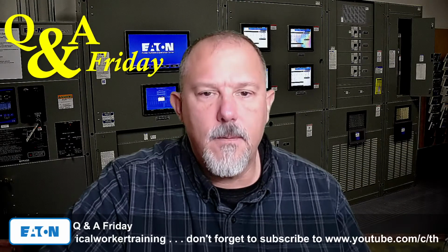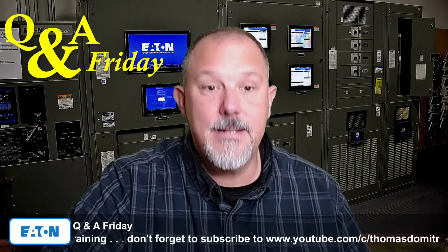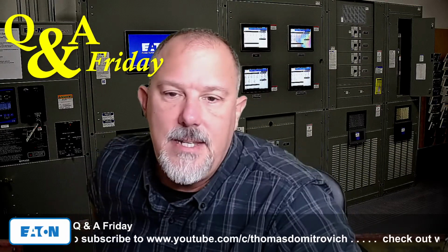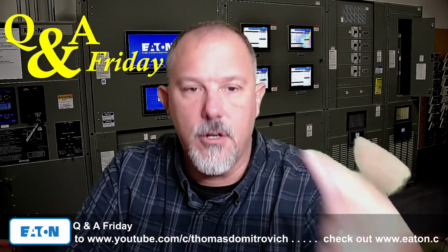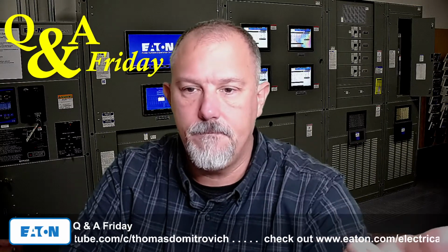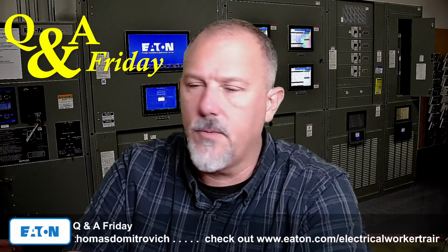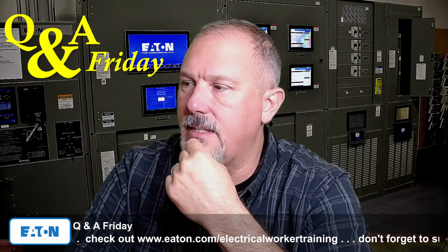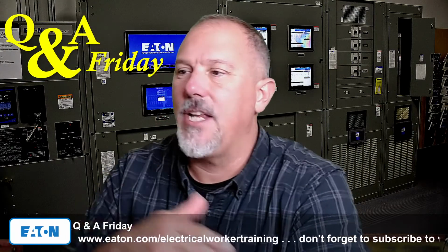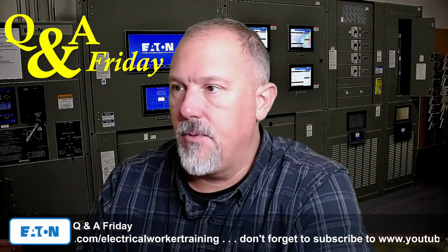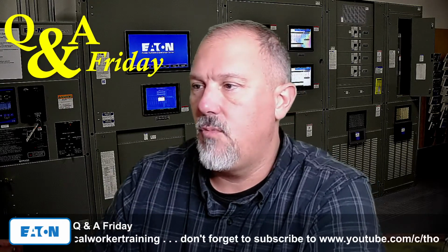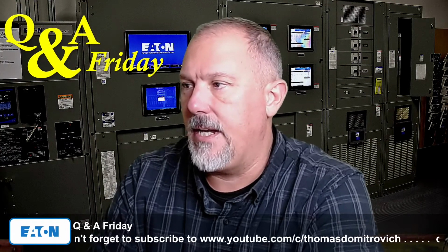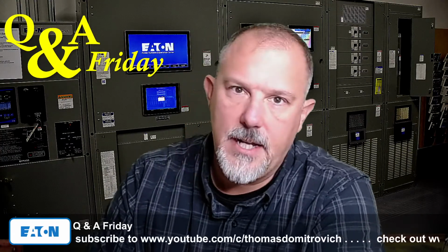110.16(B). All right. B says, in other than dwelling units, in addition to the requirements in 110.16(A), so in addition, you can't satisfy this by 110.16(A), and hopefully we can agree on that one. So in addition to 110.16(A), a permanent arc flash label shall be field labeled or factory applied, to service equipment and feeder supplied equipment rated 1,000 amps or more.